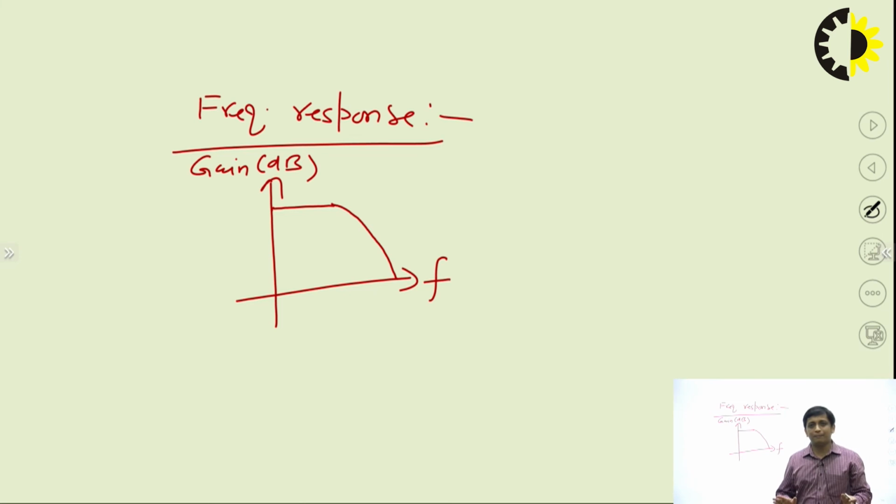But for any amplifier, whether we are using coupling capacitors or not, at high frequency the gain will be reduced, because at high frequencies the gain is reduced due to parasitic capacitances, due to internal capacitances. And of course, when we are designing an amplifier, it means that we are using transistors, and there are various internal capacitances present inside the transistors, whether it is BJT or MOSFET. So at high frequency the gain will decrease because of the parasitics.